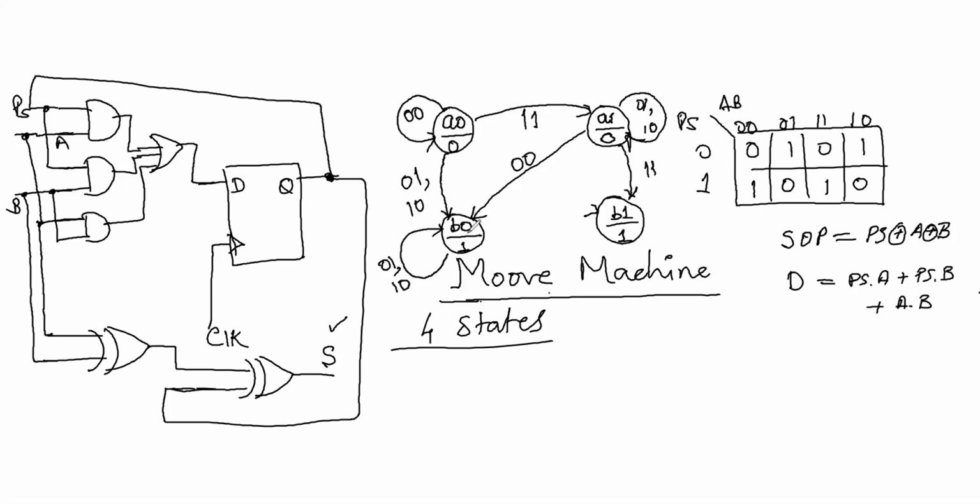So you will be here. Okay, the fourth case is left out from here, 1, 1. So if it is 1, 1 and partial carry is 0, so you will get a sum as 0 and partial carry as 1. So you will go over here.